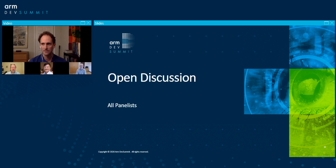I think what often happens is that you'll take one of the classic vulnerabilities, whether it's Meltdown or Spectre or some of these side channel vulnerabilities, and a mitigation will be added more broadly. We saw the performance impacts that Meltdown and Spectre had, where it really dramatically reduced performance. A lot of the mitigation techniques for side channels really are more holistic. You buy an entire mitigated root of trust or an AES engine, for example. But if you use a process which focuses on what threats you're trying to prevent against, and you build that into your process, you can sprinkle mitigations and focus your efforts in a way that dramatically reduces the power, performance, and area overhead.